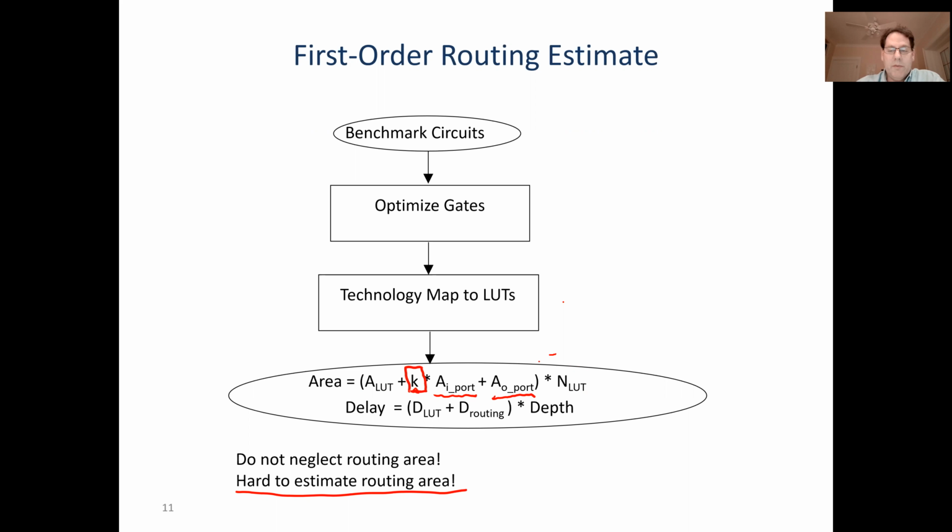That's because of the channel width that I need. If you think of what I'm building here, I'm building a bunch of lookup tables. My logic block is just a single lookup table, and they're connecting to all these programmable wires that are passing by, because I'm building an island style FPGA. So there are muxes going in, and there are muxes that I'm building to drive these various routing wires.